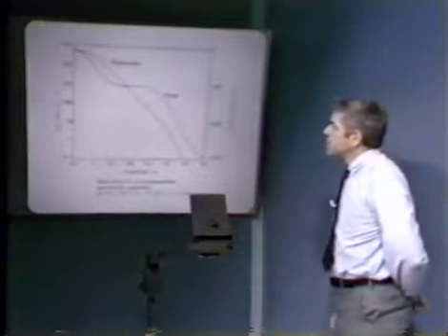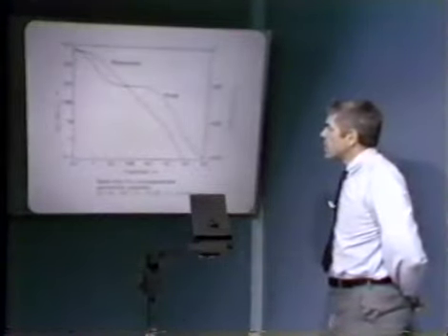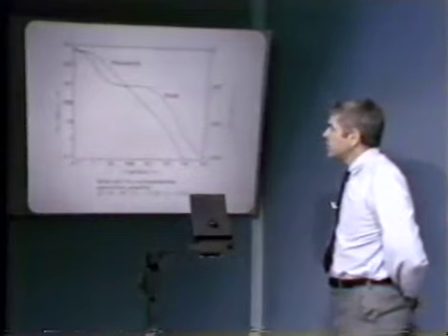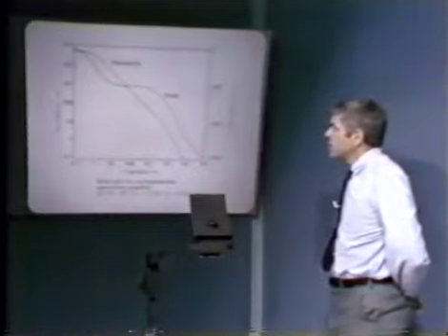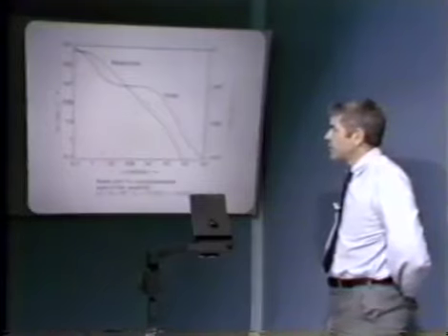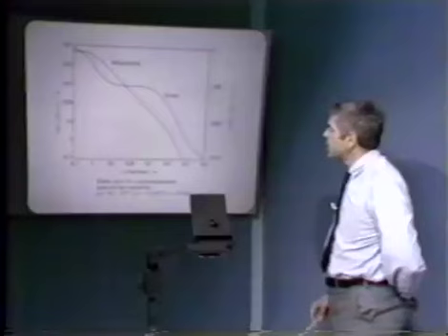This is, of course, the gain, or the AF plot, the negative of the loop transmission plotted in Bode plot coordinates that we get for our uncompensated gain of 10 amplifier. We combine the A of S associated with the amplifier with the factor of 1/10 that equals F.